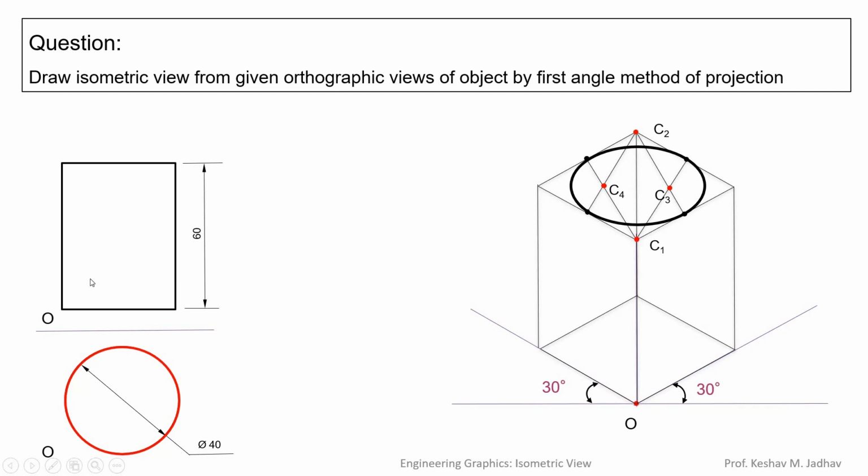Now as this is the cylindrical block, at the base side also there will be a circle. So we can repeat the same procedure for this rhombus, or here in this case the diameter of the top side and bottom side will be the same, so we can just shift the centers by 60 mm height. So this base circle is at 60 mm in the downward direction.